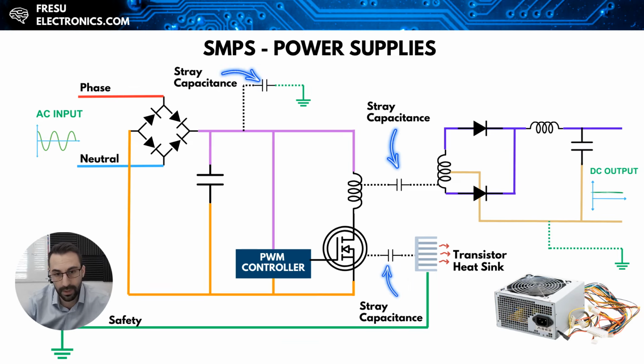The main takeaway here is that we have to think in terms of parasitic paths that emerge from the system design and connection, especially how these parasitic paths will influence the test at the specified frequency range of the test, and also can result in effective current loops for the common mode currents. Now, let's address how to solve the issues related to the differential mode currents.